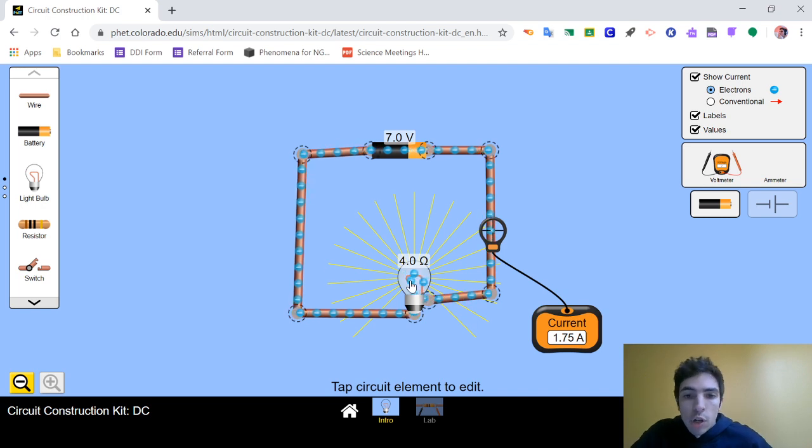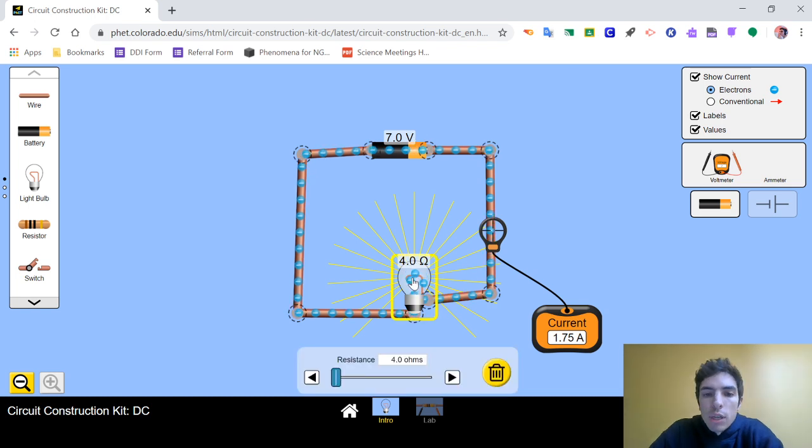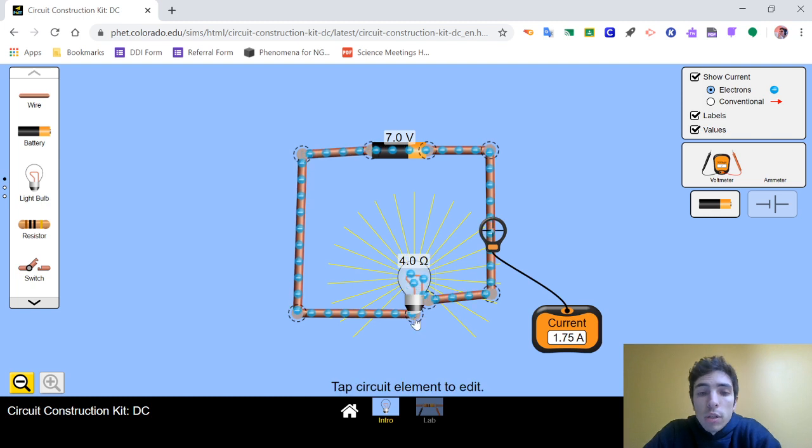And for your work today, you're first going to use those default numbers, which if you take a look back, I might have just accidentally given the answer to. But then you'll also see what happens with the default 9-volt battery as you increase this resistance to 20, 30, and 40 ohms, and you'll measure the current with this ammeter there.